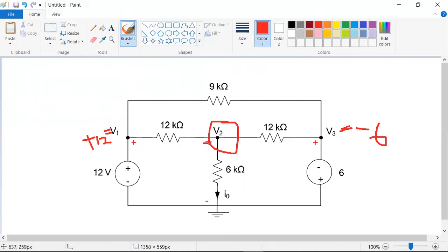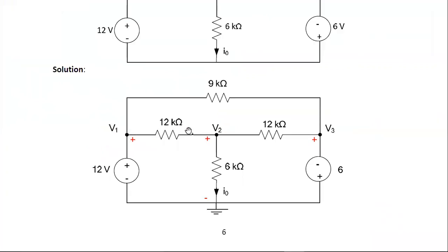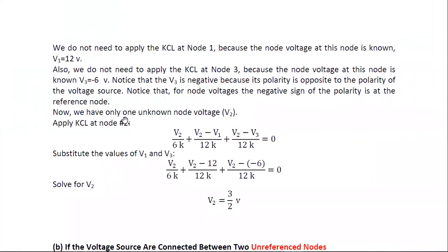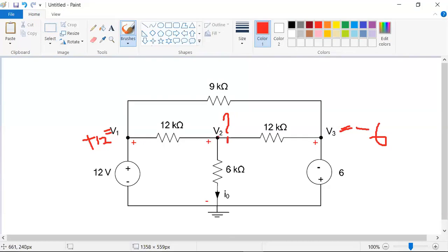That already you given the indication of plus and minus. V2 is unknown now, right? So you need to find this V2. For the finding of V2, you should depend upon this 2 volts. So hence, at node 2, just apply the KCL, because current is leaving from this unknown node voltage.